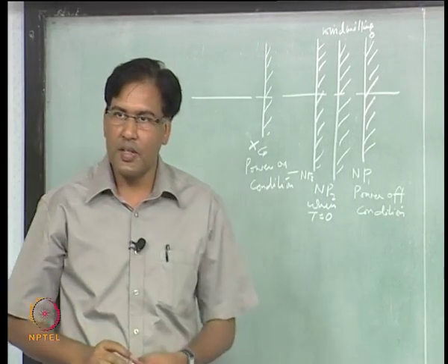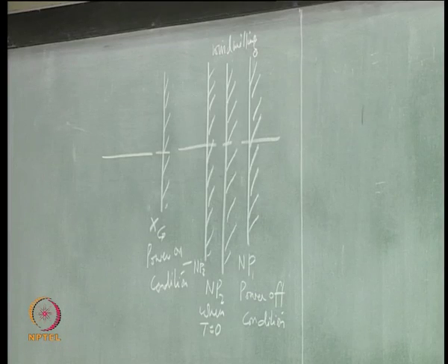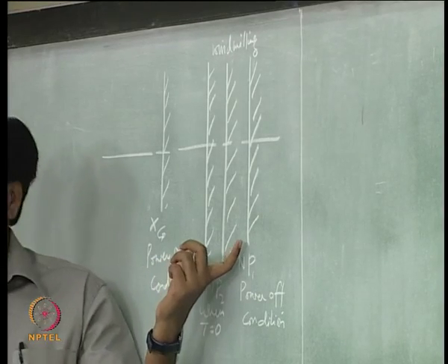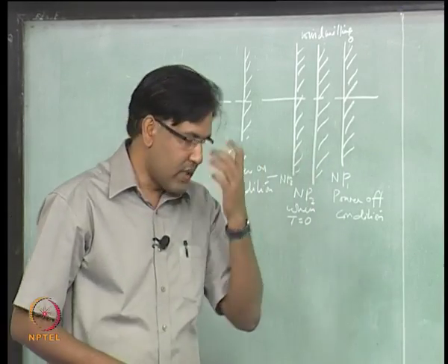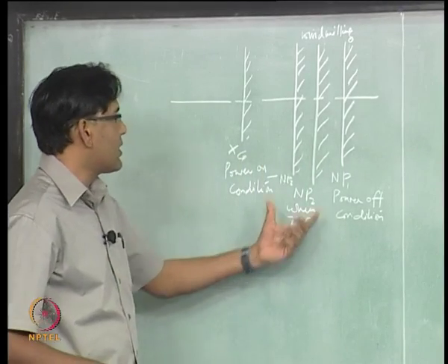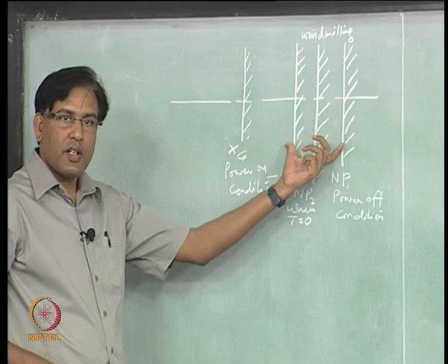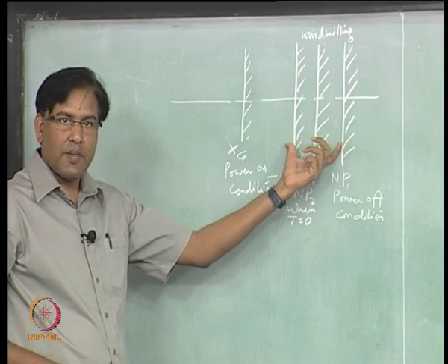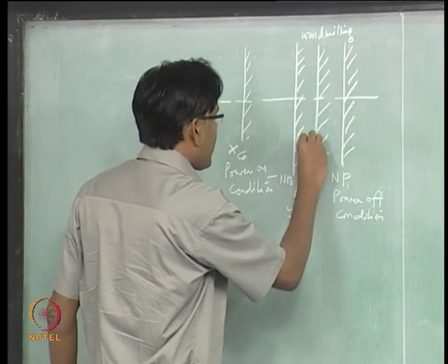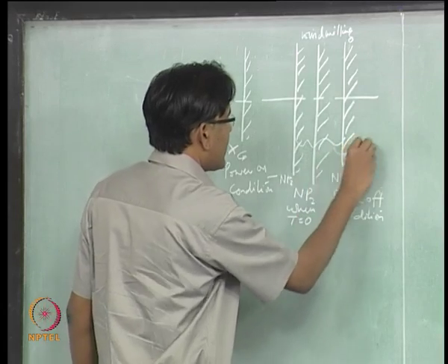I think both of them are same, okay, stability margin or static margin. So, clearly you can see that when you start running your propeller and the engine starts producing thrust, then there is so much of decrease in the stability margin, right.